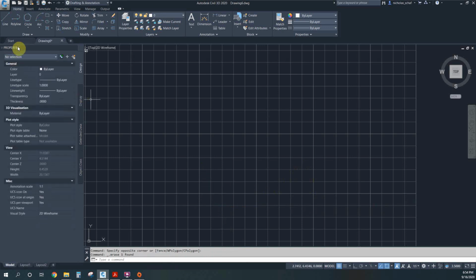So that is start, center, end, start, center, angle, which then asks you for the angle that you want it to be. And that is the opposite side of your cursor. So you can see just to the bottom right of my crosshair there, you can see the dashed yellow line. And if you spin your cursor or your crosshairs, you will see that the complete opposite side of the arc is where it's dragging it. So that is how you do that one.